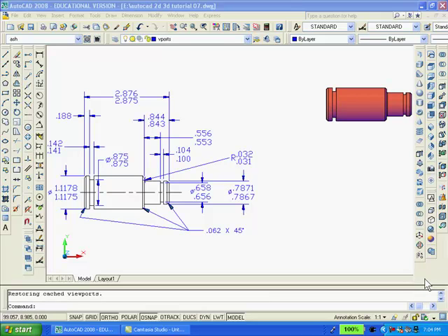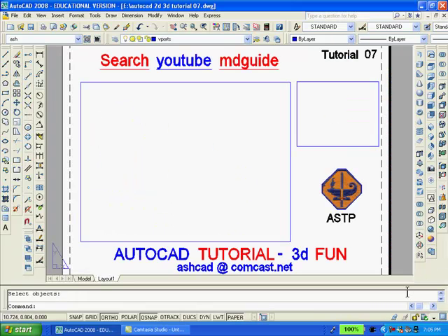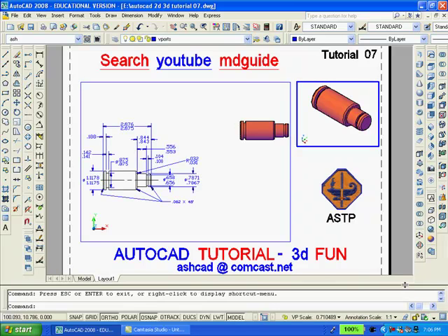Having finished the 2D solid model and dimensioning, I want to get back to Paperspace to view the drawing properly and make it ready for printing, so I'll click the Layout 1 button. As you can see, my template rectangles are still there. Now to create the two viewports, I'll type MView and select two diagonal intersections to create the larger and smaller viewports. I'll double-click inside the smaller viewport and switch to Southeast Isometric View, then pan and zoom to enlarge the model. To get back to Paperspace, you double-click outside the small viewport.